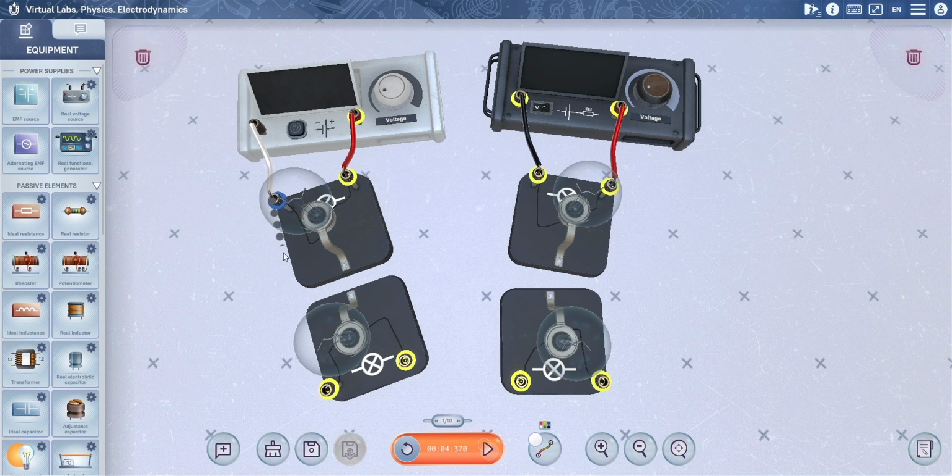You can run wires of different colors between the object's terminals. The color of the wire needs to be set beforehand. To create a wire, click two available terminals that you want to connect, or click and start pulling on the first terminal and release on the second. If you do not want to continue creating the wire, deselect the terminal. To change the color of the wire, you will have to remove it and create another one.